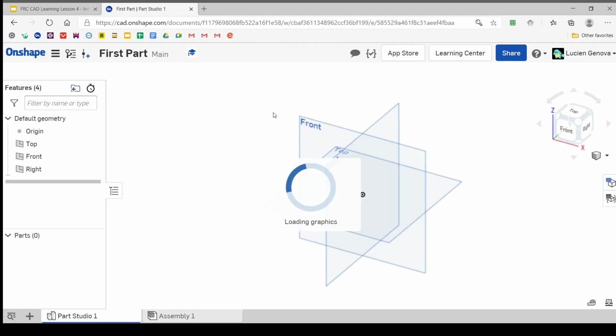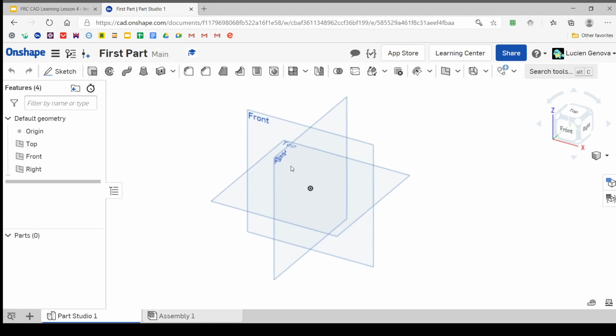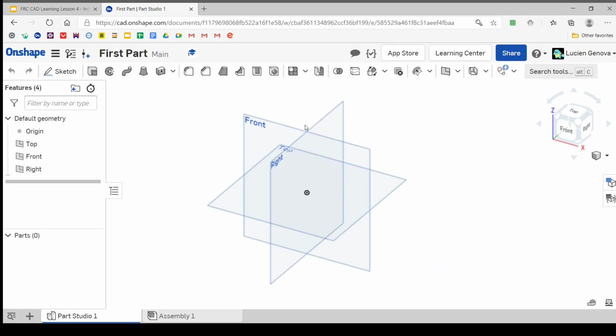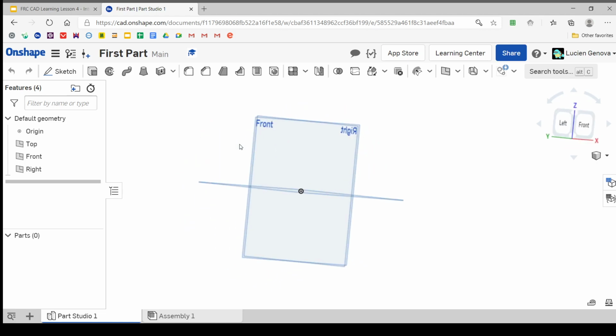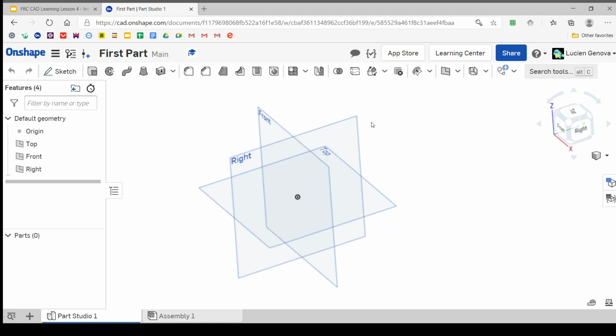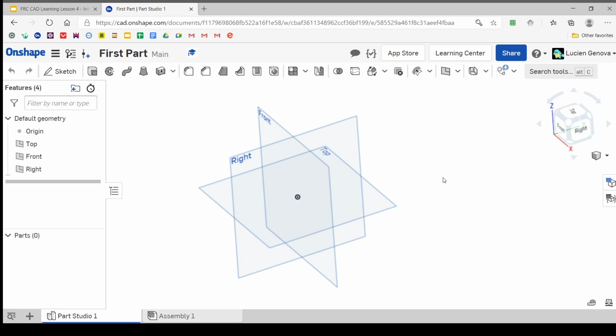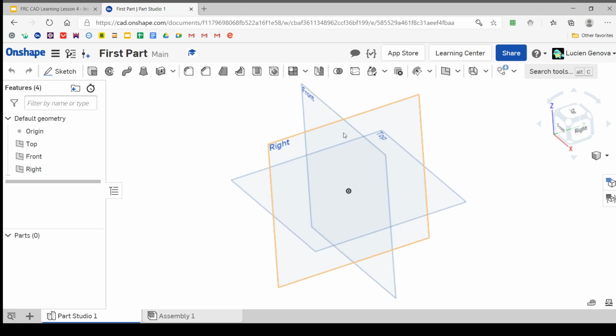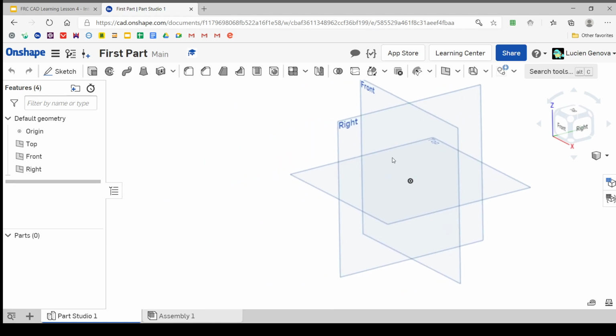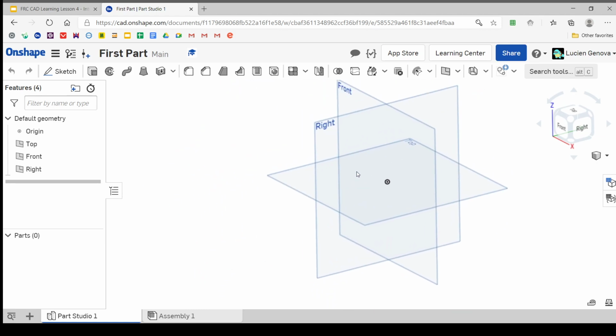So you have this 3D viewer, this graphics area, and when you're using CAD, spoiler alert, it's really helpful to use a mouse. I don't know if that's a spoiler alert, but it is a helpful tip, because then you can right-click and drag much more effectively in order to orbit like this, right? This is me right-clicking and dragging. Then you can also right-click on different locations in order to get different options based on the context of where you click. And you can also middle-click with the scroll wheel to drag this around, to pan.